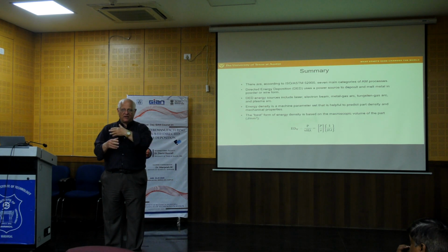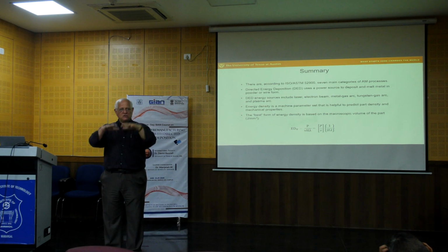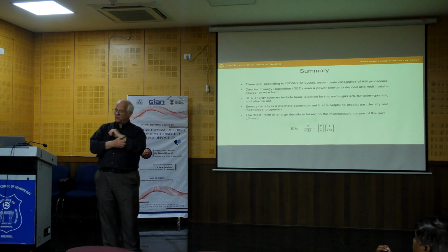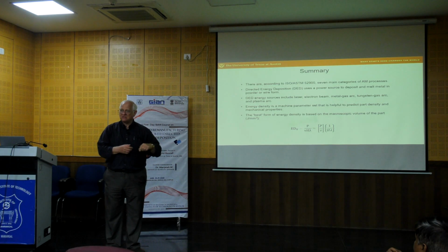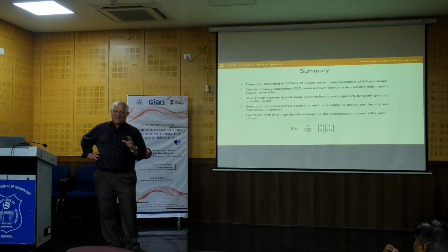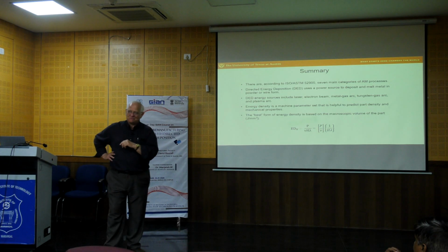And so basically they could lay the carbon black down very quickly into nylon powder, say, and then they could just plaster the whole surface, and you can build parts very quickly that way, because we don't have to scan a laser beam over the entire surface with a scan path. That's half of HP's process.